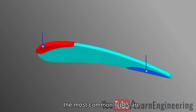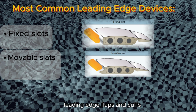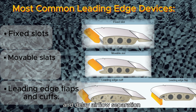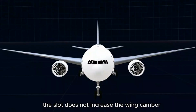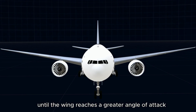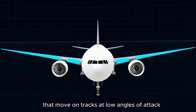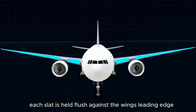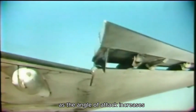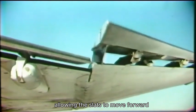Leading edge devices. The most common types are fixed slots, movable slats, leading edge flaps, and cuffs. Fixed slots direct airflow to the upper wing surface and delay airflow separation at higher angles of attack. The slot does not increase the wing camber, but allows a higher maximum coefficient of lift because the stall is delayed until the wing reaches a greater angle of attack. Movable slats consist of leading edge segments that move on tracks. At low angles of attack, each slat is held flush against the wing's leading edge by the high pressure that forms at the wing's leading edge. As the angle of attack increases, the high pressure area moves aft below the lower surface of the wing, allowing the slats to move forward.